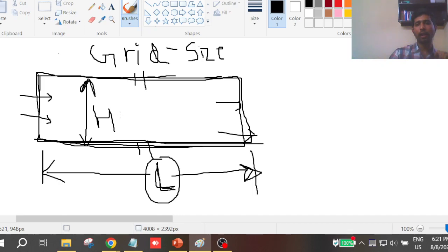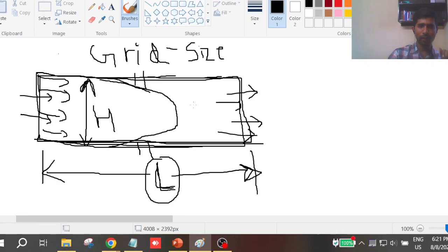Yeah, it should not affect your flow variables, because we are selecting an outlet model here. So how do you know that the flow has stabilized? Let me ask it in that way. Basically you have a very flat velocity profile in this channel at the inlet, okay. After that, there is some boundary layer which comes in, you get some profile, and after that you get a parabolic profile. So at what length should you stop? Let me ask like that.